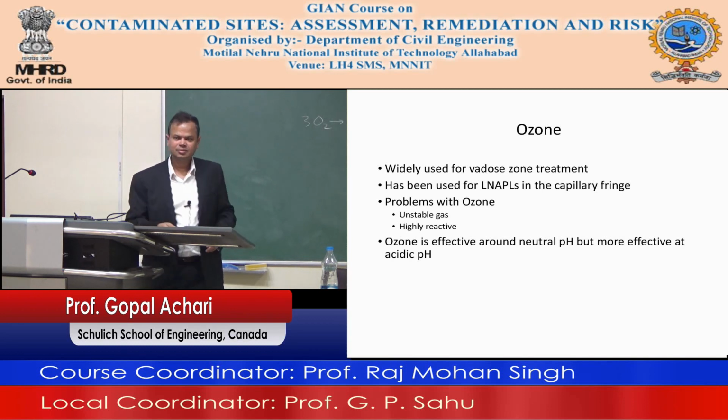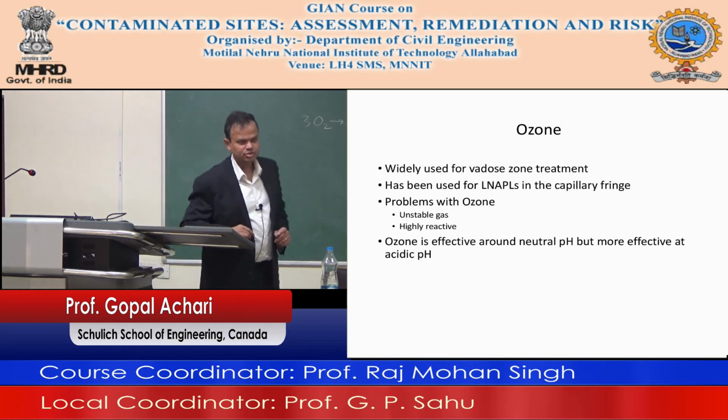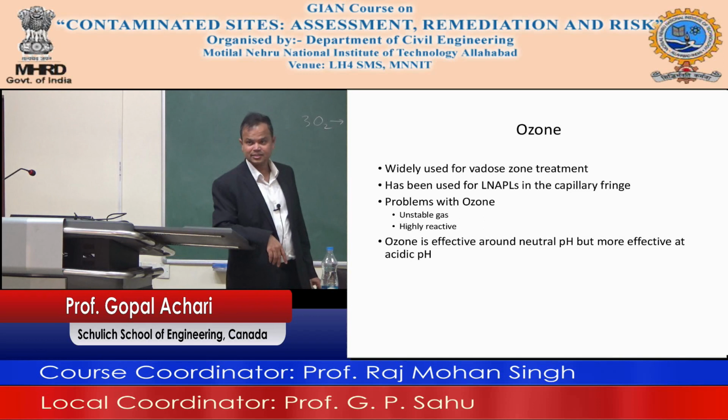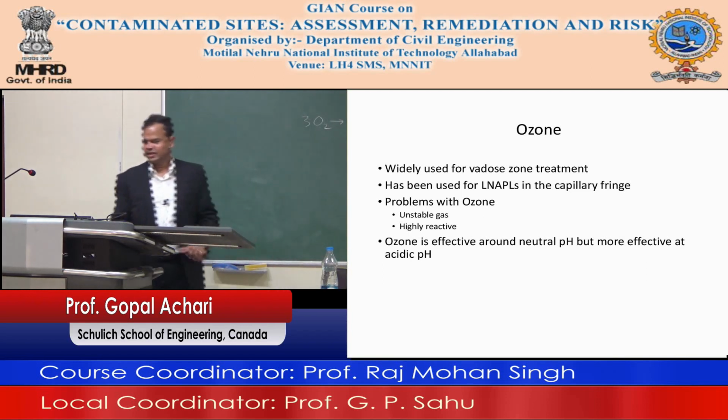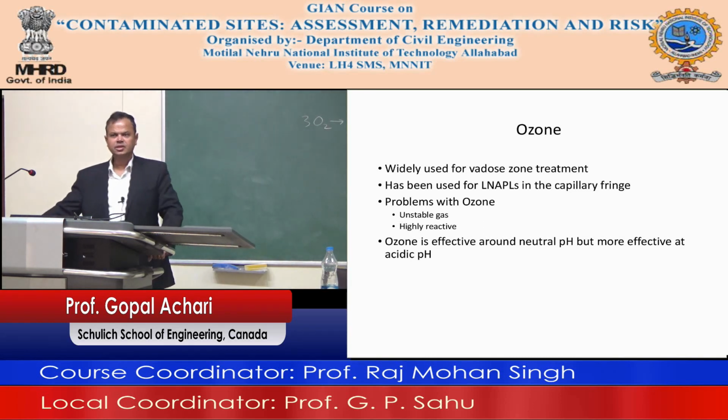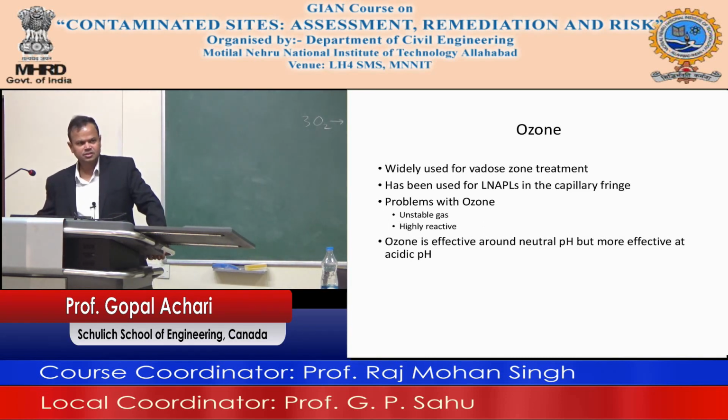As I said, it is a very strong oxidant and dangerous gas. You want to take adequate precaution, make sure there's nobody around, and give enough time for ozone to act as well as dissipate. It has a half-life of about 20 minutes, so it will be there for a while.